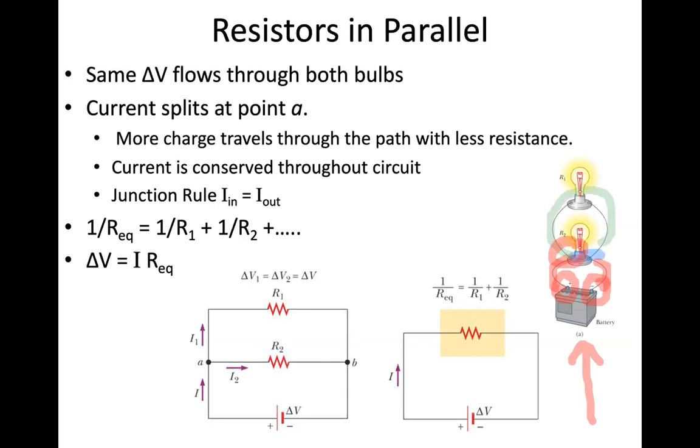So if I first of all take a battery with two resistors like this, and I want to draw a circuit diagram, I replace my battery with my battery symbol, the long side with positive, the small side with the negative, and I start following the current around. So it comes out the positive, okay, comes this way. So here we see it just says I. But then there is a junction.